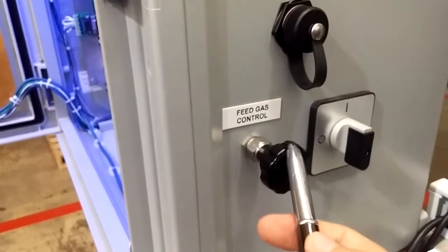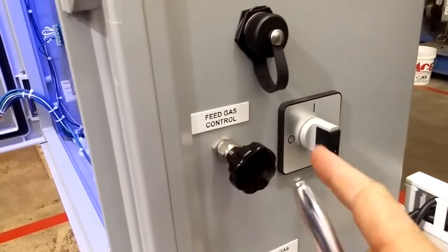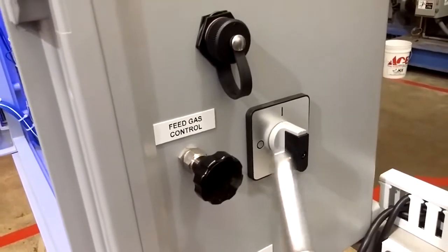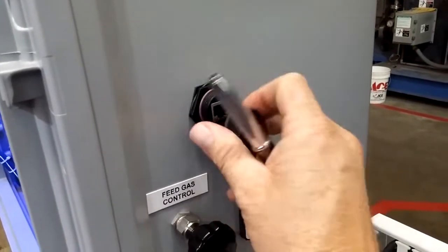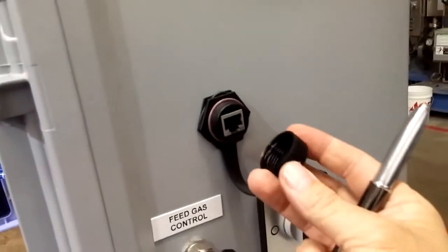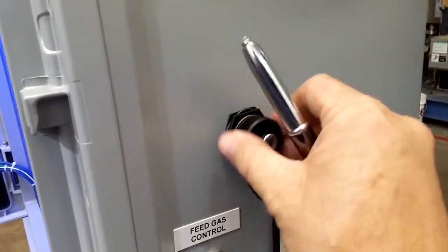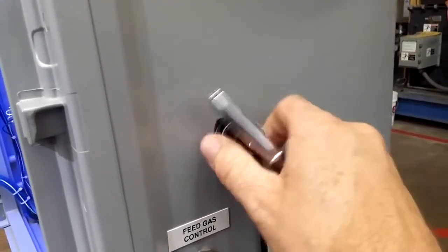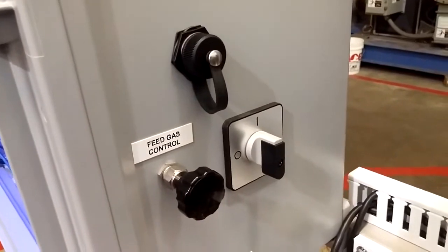On the side of the generator we've got a feed gas control. This is what regulates the gas flow through the generator. Like I said, the pressure regulator will automatically readjust pressure to maintain our target if you readjust this. We also have all these systems, as I said, Modbus compatible. We have an Ethernet port on the side and a bulkhead fitting where you can connect a computer, SCADA system, or a technician can plug in a computer with the maintenance software to troubleshoot any changes or upload new programs to the PLC.